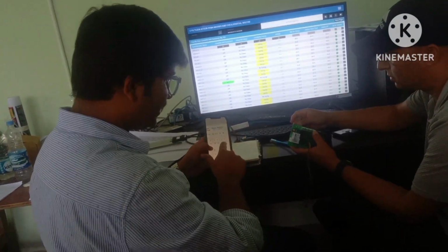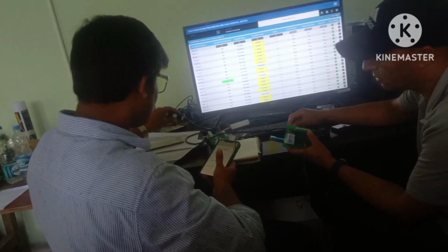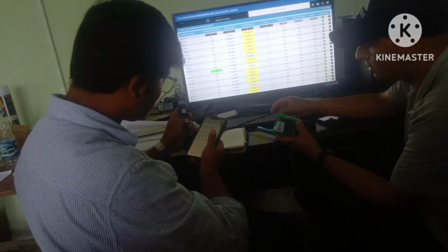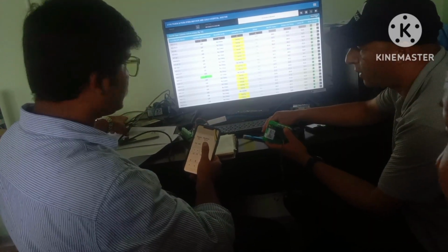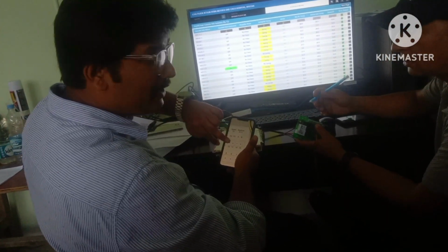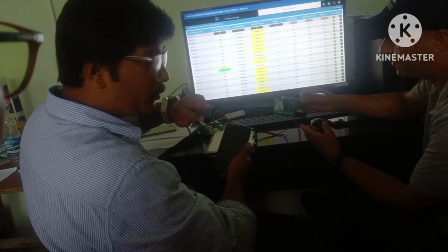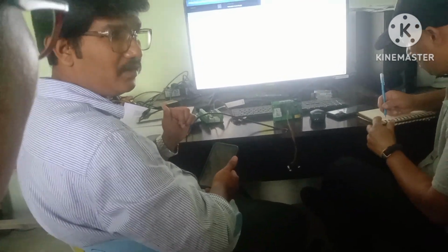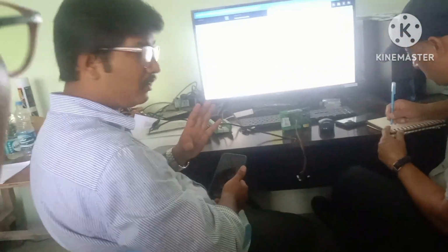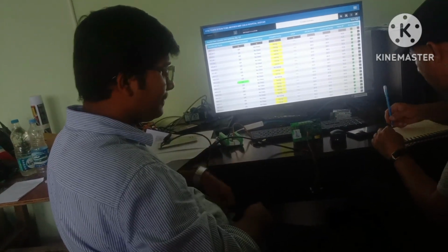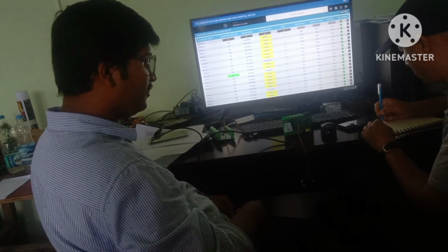Also, it is written specifically which one is A and which one is B. It's plus and minus, red and black. Always remember plus stands for A and minus stands for B. There should be no change of polarity also. If you put DC plus into minus and minus into plus, what will happen? That will fuse out. Plus stands for A and minus stands for B.